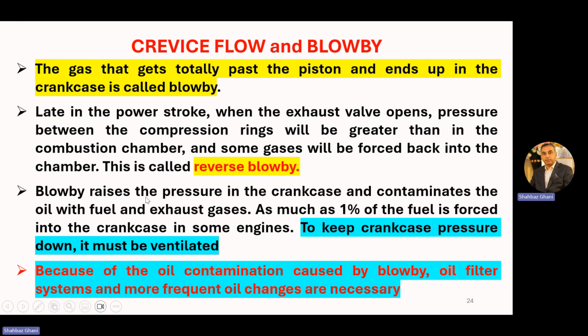So blow-by raises the pressure in the crankcase and contaminates the oil with fuel and exhaust gases. As much as 1% of the fuel is forced into the crankcase in some engines. To keep crankcase pressure down, it must be ventilated. So your crankcase, the lower portion: you have the engine head, then the engine block or engine body, and the lower portion is the crankcase or the sump. So the crankcase or the sump has to be ventilated to avoid the buildup of pressure.